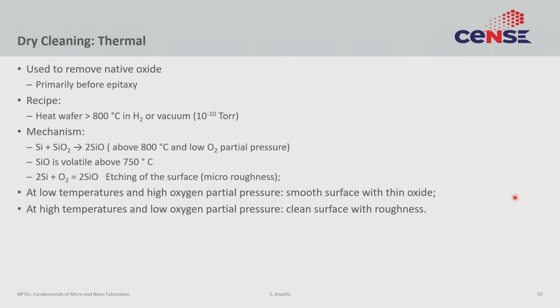The place where this is used often is in epitaxy. So, if you are growing silicon on silicon and you do not want any SiO2 at the interface, then you would do this clean before your growth. Okay. There are certain challenges at low temperatures and high oxygen partial pressures.